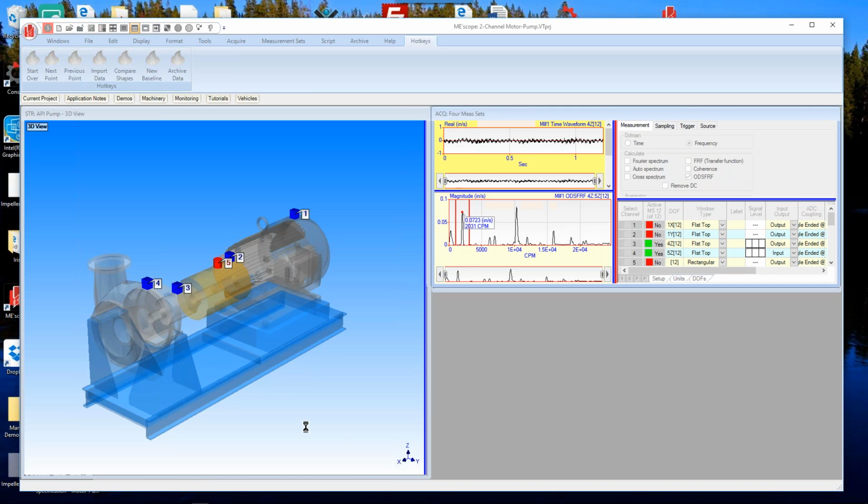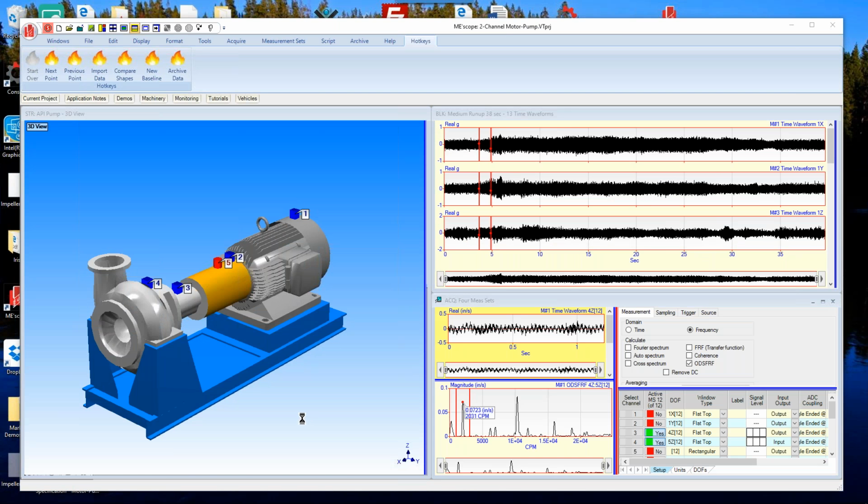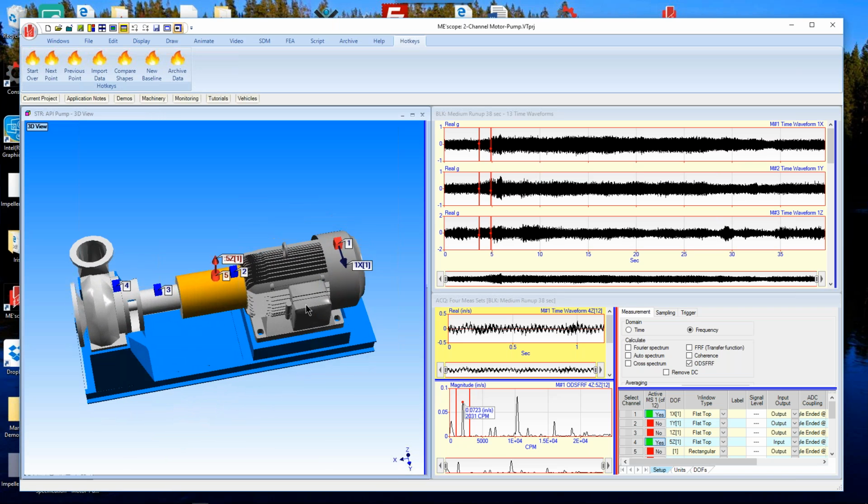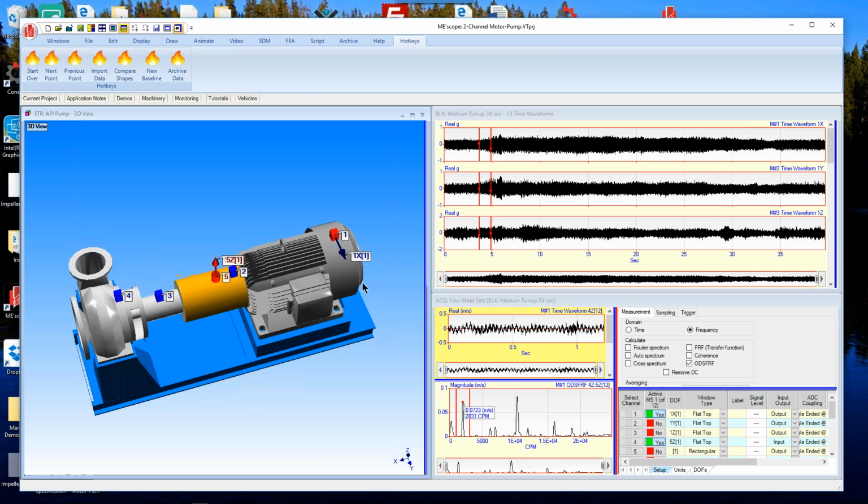And so here it is. It's opening up a number of windows, but it's come back with the same display of the acquisition window here, some data up here on the top. This is the recorded, pre-recorded time histories, and you can see here that now it's telling me, okay, here's my reference at 5Z, and here is my first measurement with a uniaxial accelerometer, 0.1 in the X.